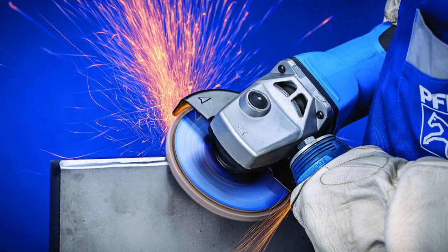Next, we have the manufacturing process. This includes the construction of the stool and the process of creating it. Firstly, we need to cut all 8 pieces of the legs to size with a grinder. Then use a flapper disc to clean off all the sharp edges and then make sure all of them are symmetrical and proportionally correct. The next step is to weld the pieces together with a stick welder. It is important to keep all of them level with each other.